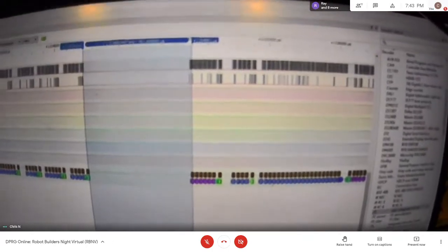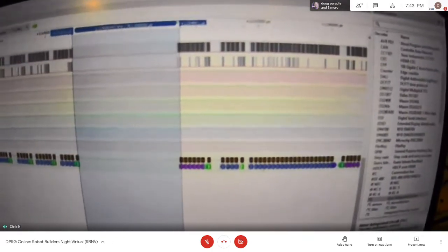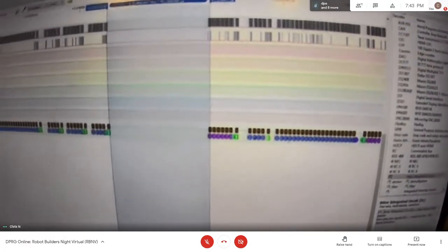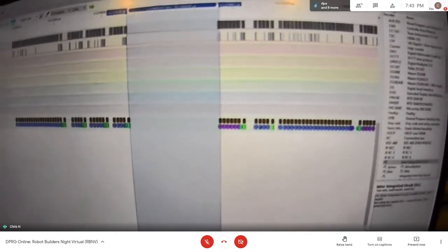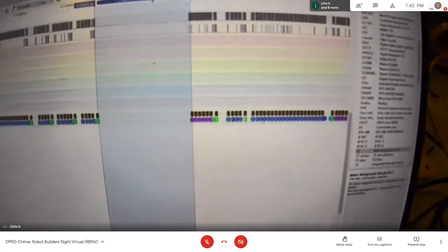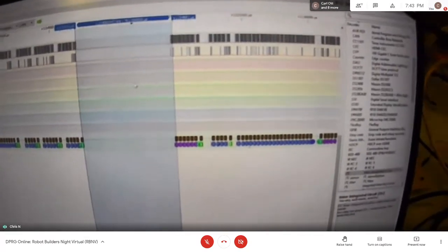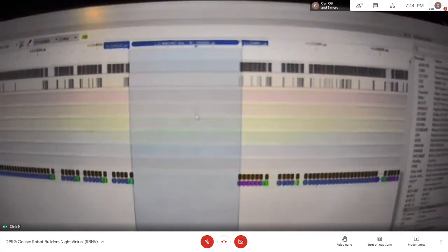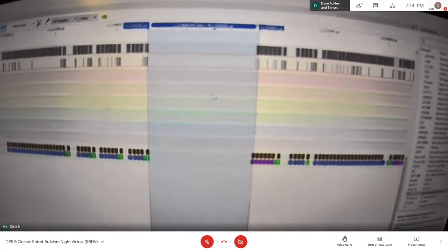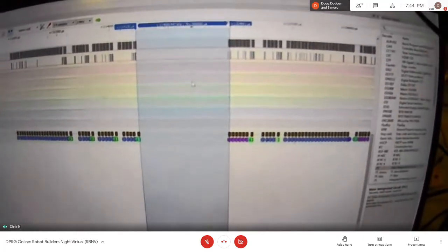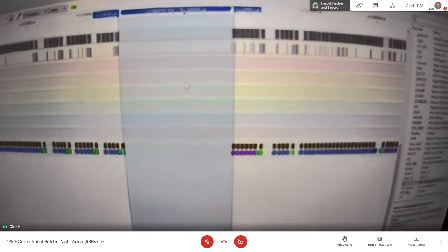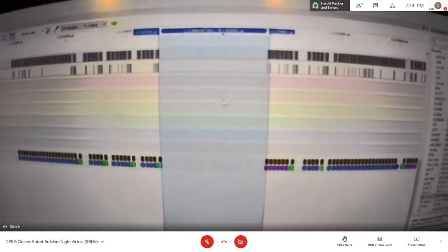But it's only today that I got my hands on my little 8-channel logic analyzer. I didn't have it for the last couple of days, and so I'm looking at that, and again I could see that occasionally the clock and/or data lines are just kept low. Now, the BNO is a very slow device. You can't read the numbers, I'm sure, but right now that blue stuff in the middle is about 800 microseconds, and that's clock stretching in action. That's the BNO holding the clock line low until it's ready to give data.